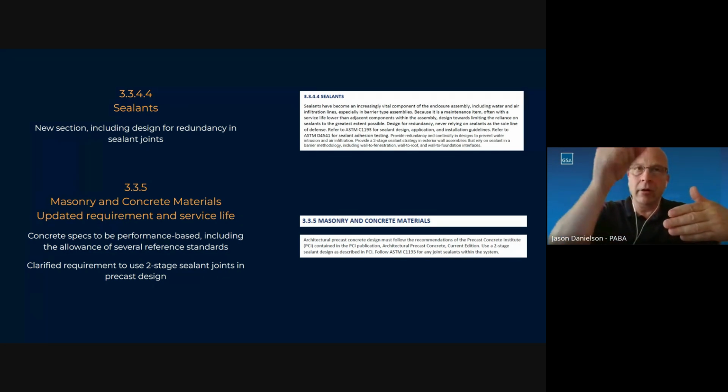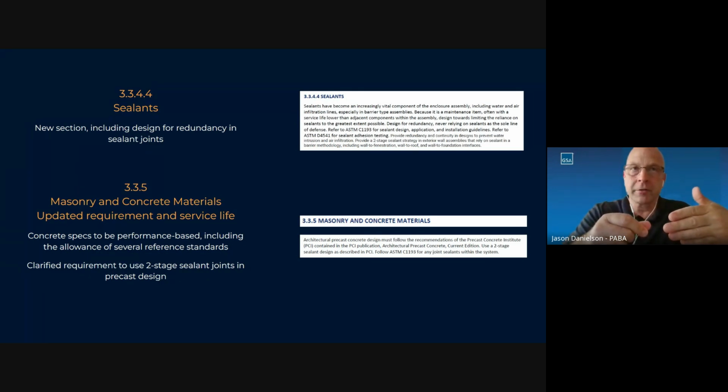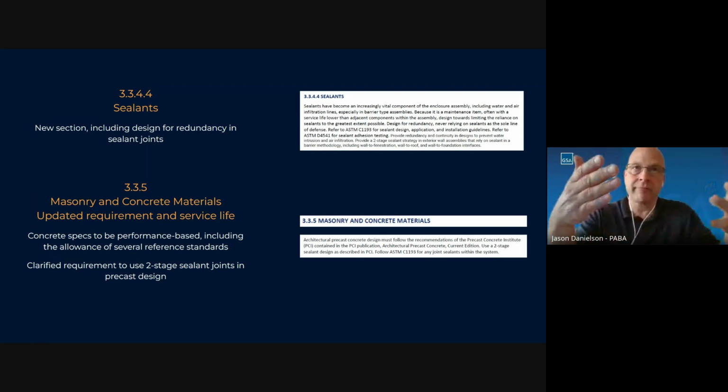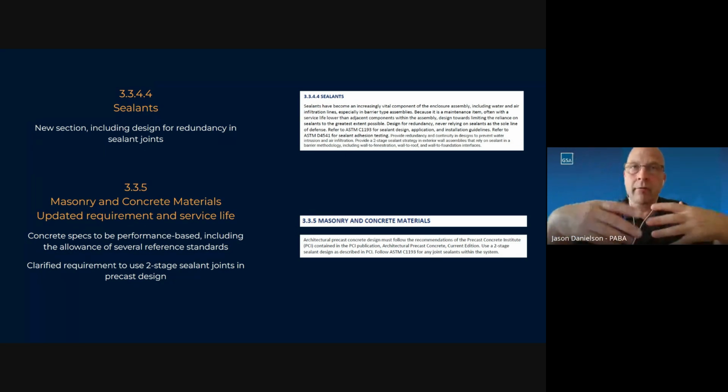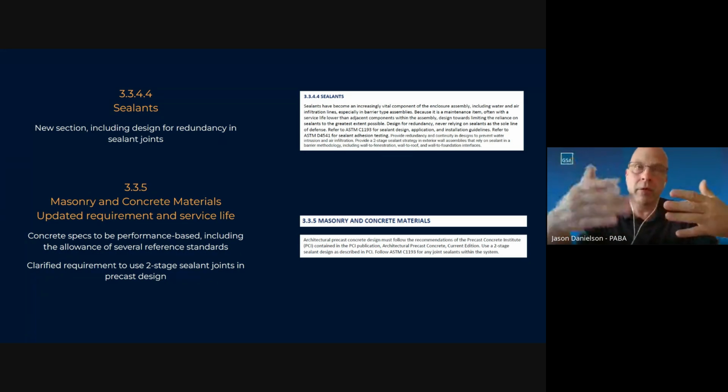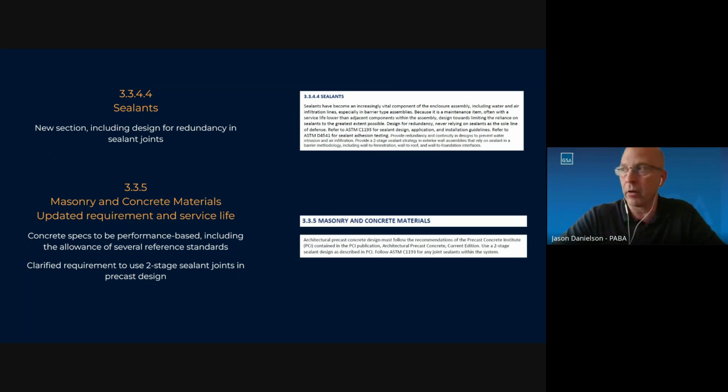And then that outermost line is really, for all intents and purposes, a rain screen. That outer line will deteriorate quickly, within 10 years, 5 years, whatever that is, maybe 20 if you're lucky. But having that interior be your primary and protected, that can go longer. And so it's really just a matter of replacing that outer line.